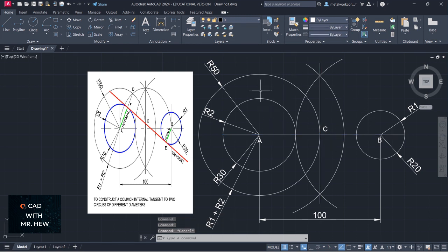All right, at C, which is right where these two lines intersect, I'm going to draw a semicircle. Now, depending on which side you want the internal tangent to go through, you would either put it at the top or below. So I want my internal tangent to go from the left to the right. So I'd have to draw the semicircle above. All right, let me show you.